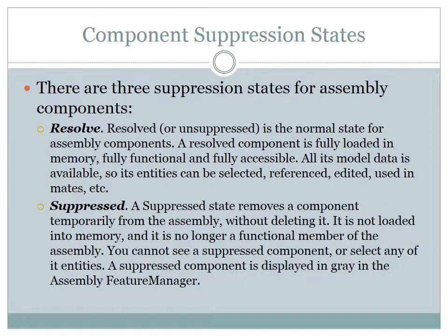There are times when you want to or need to suppress a component or assembly. There are three suppression states for assembly components. Resolved or unsuppressed is the normal state. A resolved component is fully loaded in memory, fully functional, and fully accessible. All its model data is available, so its entities can be selected, referenced, edited, and used in mates.